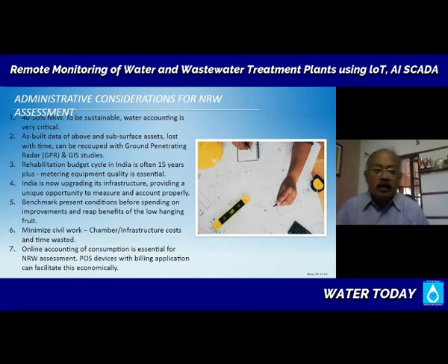Now, one thing that we would like to suggest for municipal corporations, which again is happening in one of my projects, is a GPR study. GPR is ground penetrating radar, which helps you to identify all the major pipes which are below ground. The supply source pipes, the bulk water transmission and distribution pipes, and then the local pipes, in each area there are 100 dia, 80 dia, 110 dia, 150 dia pipes which are distributing water in each area. All these pipes and pipe material can be identified and recorded very accurately. The locations can be identified. You can put them in a system where it is available for you readily. If you are losing water in a particular area, at least you know where your water network is. So you have a good chance of doing something about the losses.